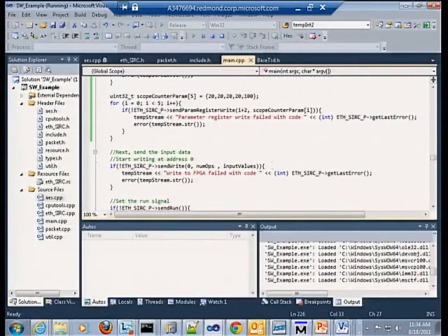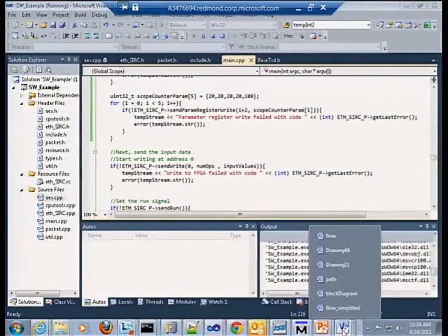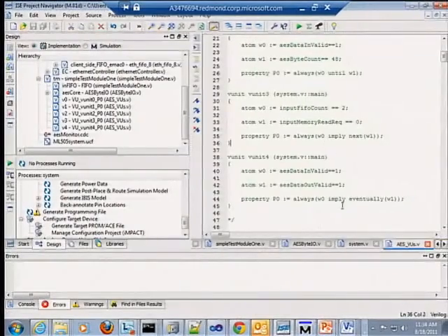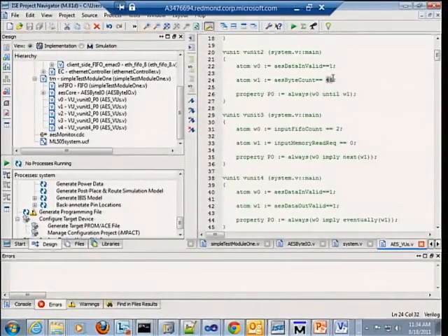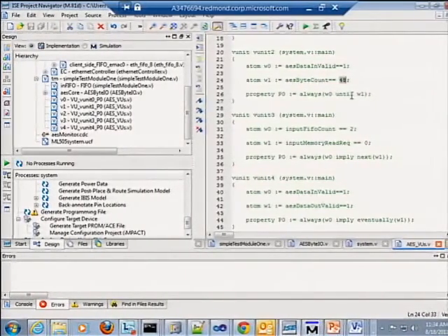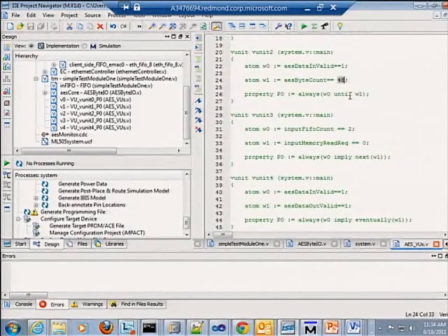Also, I was talking about parametric assertions. Let's see. There are certain ways you can parameterize your assertion. For example, I can pass on the value 48 from software to the assertion. So I don't have to resynthesize these assertions every time I want to change these parameters. So in certain cases, you can parameterize assertions. So you can pass on these values to the assertions from the software. So you can add more flexibility to the tool.